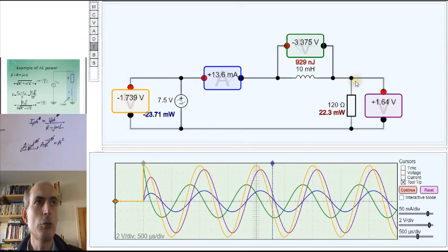And if the voltage across the resistor is positive, then the current flowing through the resistor must be going top to bottom, which means the current is flowing around this circuit clockwise. That means that at these particular intervals of time, the voltage source is actually absorbing energy.